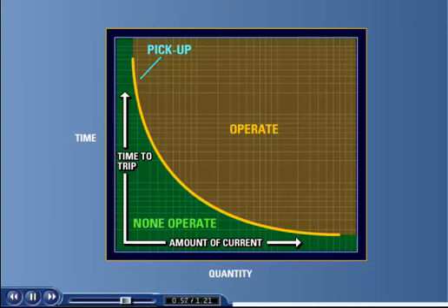It is common for the curve to be drawn such that it does not extend to either axis. When the curve is drawn like this, it is implied that for every value of x beyond the curve, the value of y will remain the same. A very common requirement is to remove a component if the amount of current flowing into the component exceeds certain levels over certain amounts of time. The time and instantaneous overcurrent elements were created for this purpose.